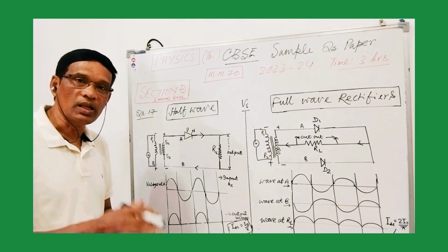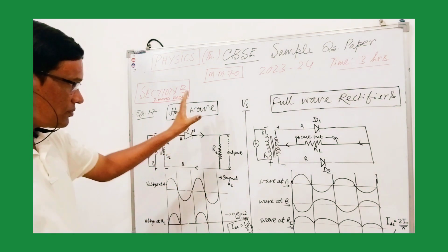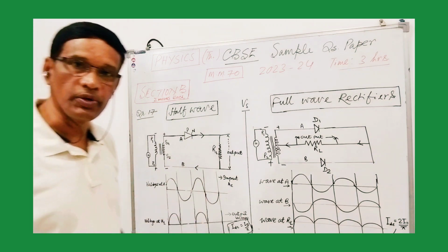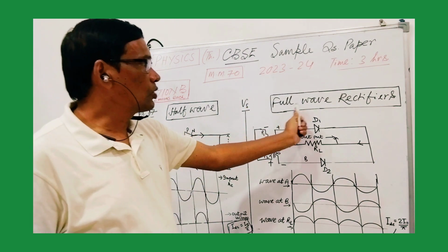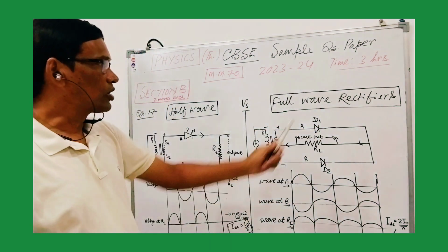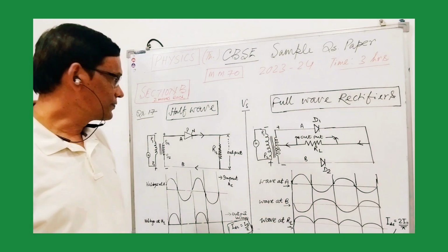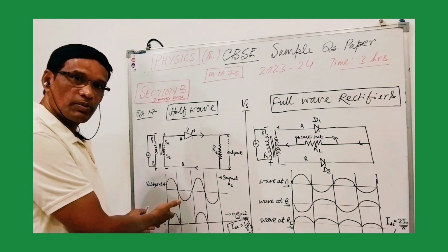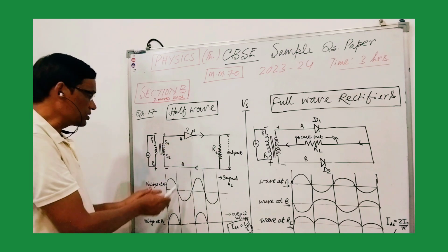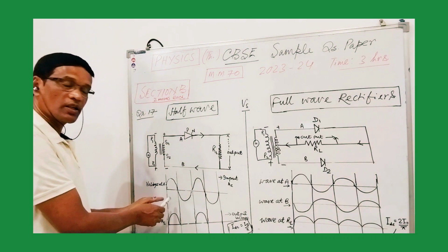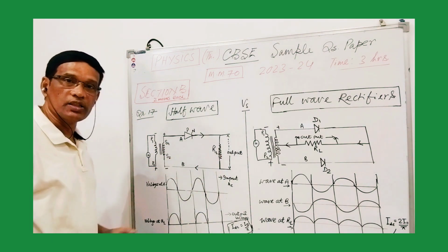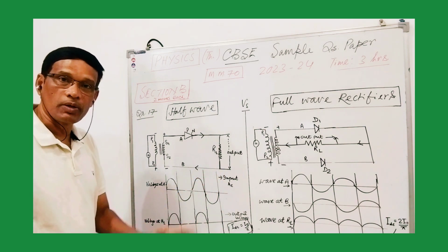Frequency of the AC. Okay. This is what is called a half wave rectifier. And quickly let us see what we do technically for the full wave rectifier. Right. So as you see, what is the demerit here? When the P is fed with the negative signal, unfortunately no load is developed at that time.